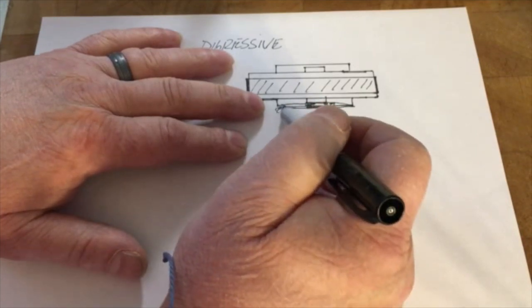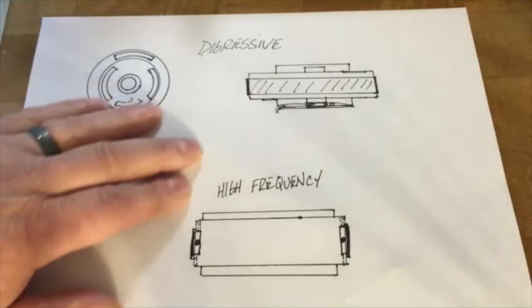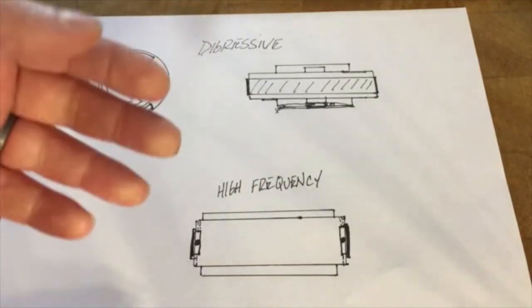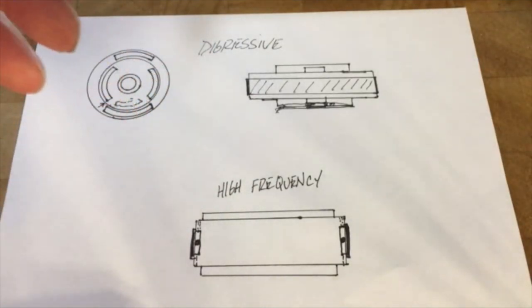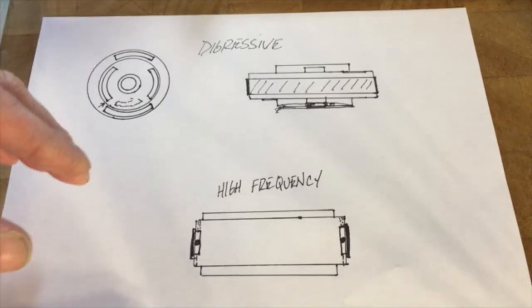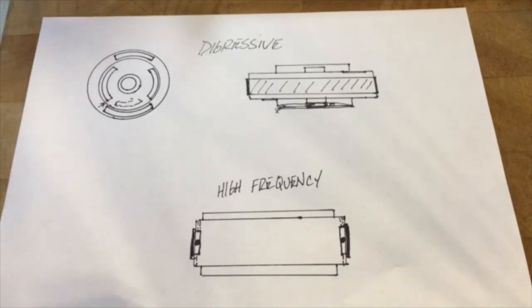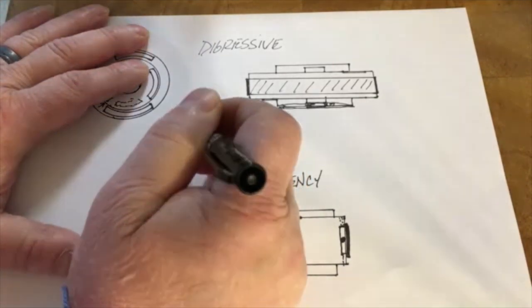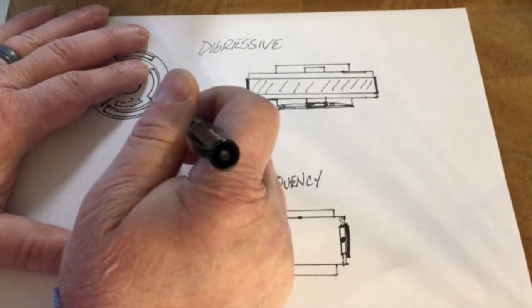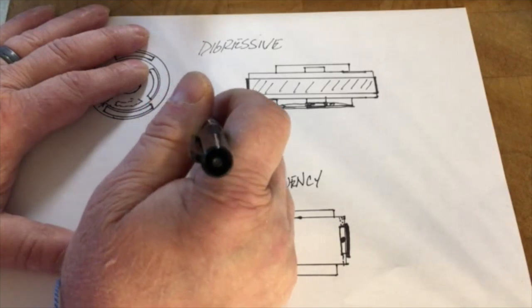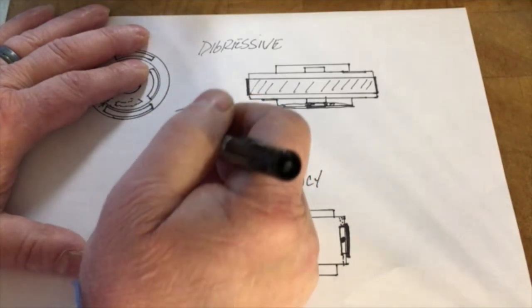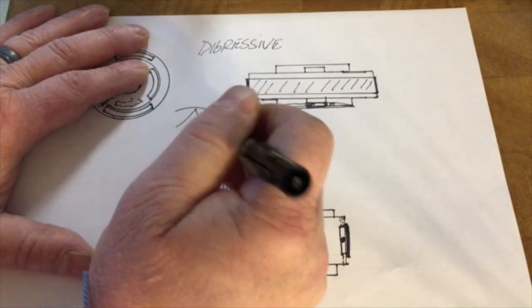this would open up almost like bleed, but it wouldn't be as sloppy. You'd have at least a little bit of control at the top and bottom. As we were looking at shock diagrams last week and shock dyno graphs, that would be if your dyno graph was actually kind of smoothed out on top instead of so pointed.